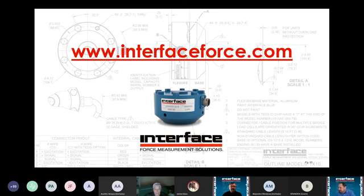So. Frequency measurement limit, how fast the load cell responds. Another great question. That's obviously going to be a function of the particular mechanical flexure design for that sensor. Each sensor, again, as Keith said early on, is a mechanical spring, if you want to think of it that way. So depending on the stiffness or the deflection characteristics of a load cell, you will have different natural frequency characteristics. That's usually documented on our data sheets, so you can get an idea. But generally, the stiffer the sensor, the better it's going to perform in cyclic applications.